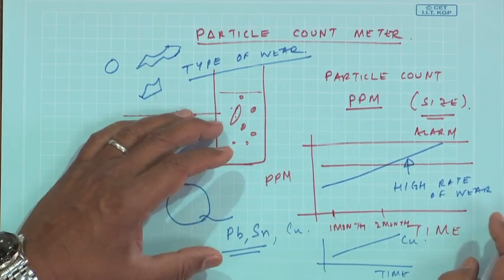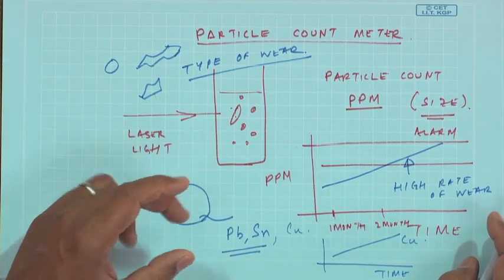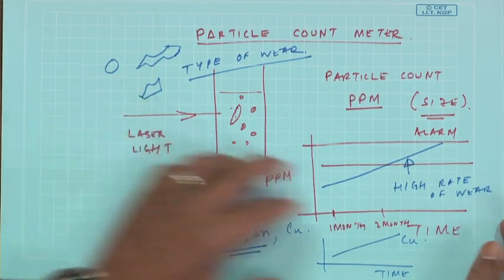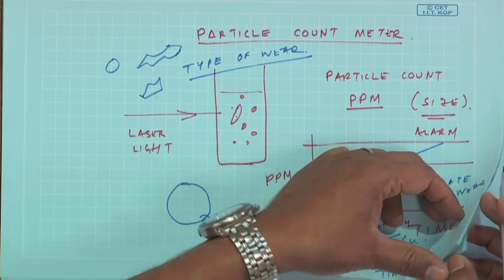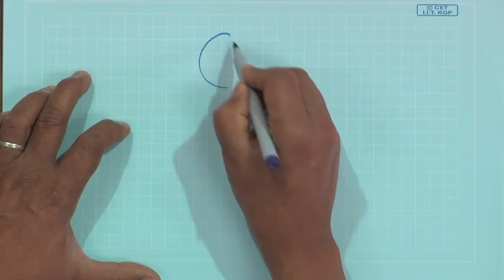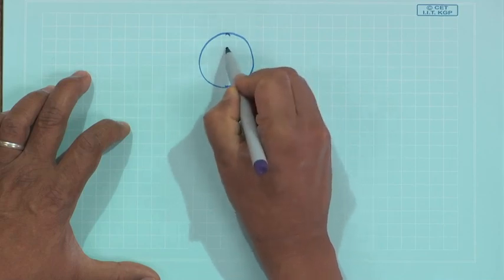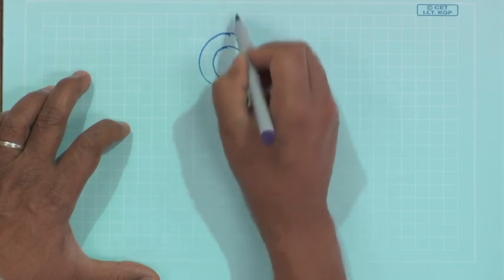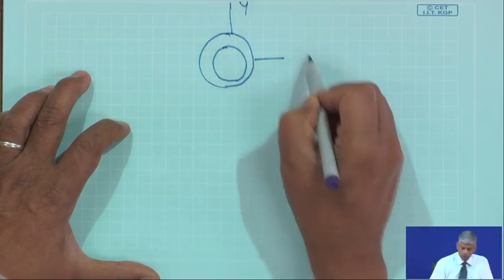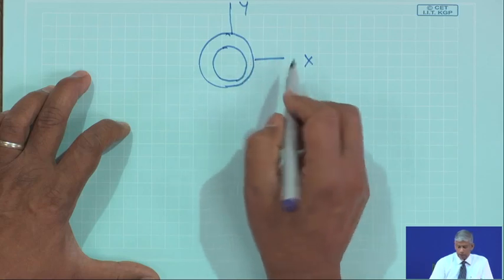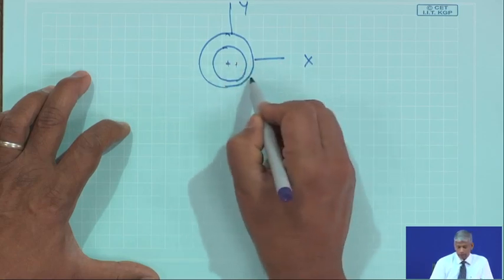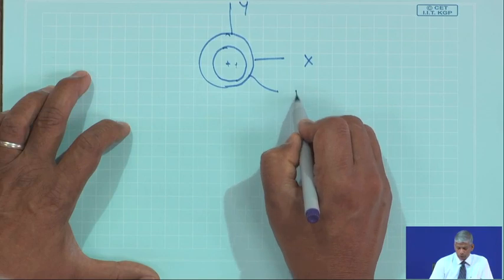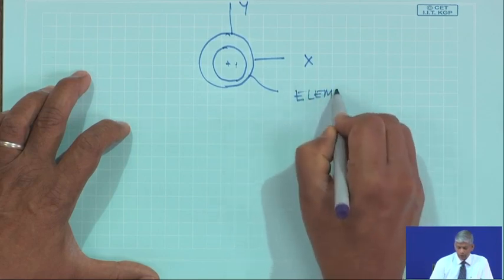So, these kinds of observations, very specific to a particular element, can only be done with wear debris analysis, because if you think of journal bearing monitoring, at most I can measure through vibrations that the clearance has increased or decreased. The gap has increased or decreased through an eddy current probe. If this gap has increased, but the element composition can only be done through spectroscopy.